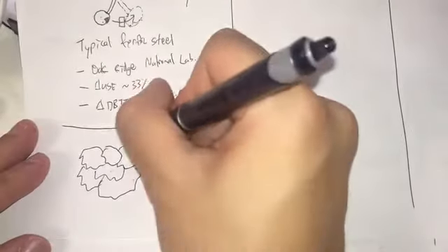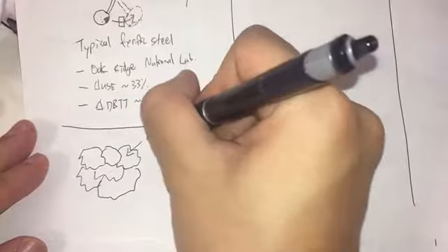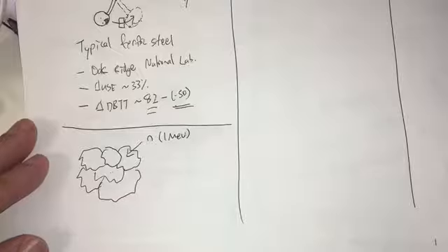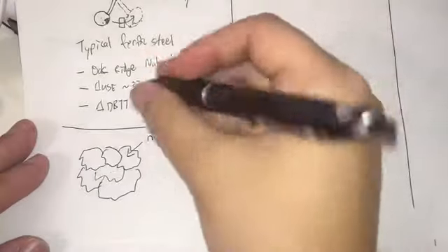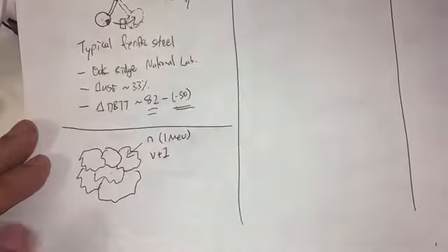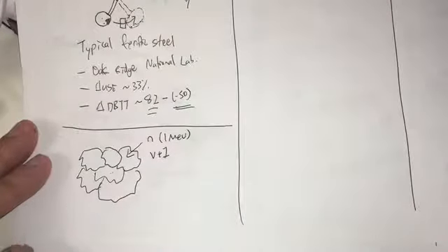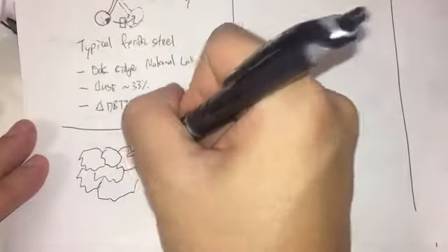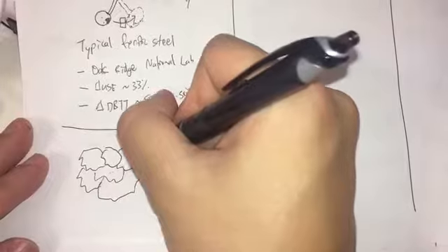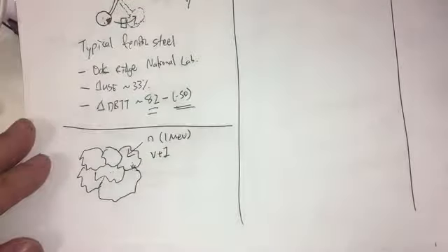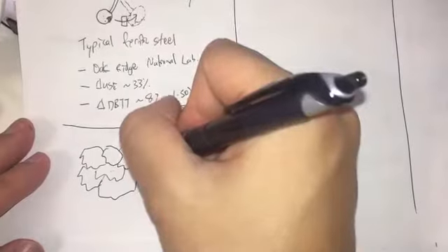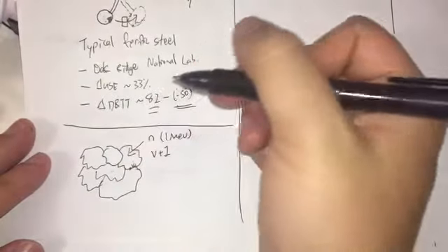When a neutron with maybe 1 MeV plus of energy hits this lattice, you will have Frenkel pair generation, a vacancy and an interstitial. These defects, for example the vacancies, will start migrating towards the grain boundaries, because the defects like to coalesce at the grain boundaries.